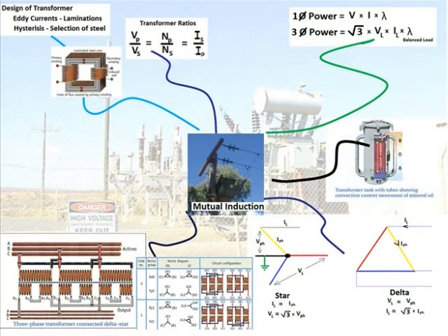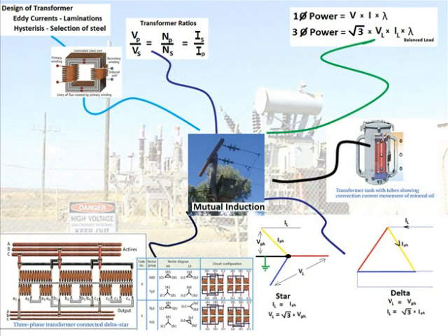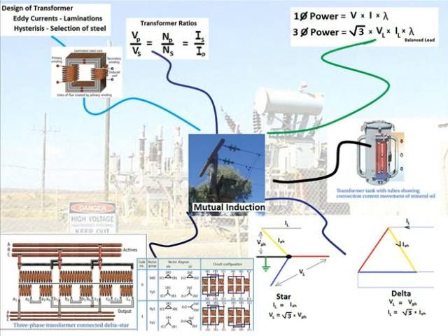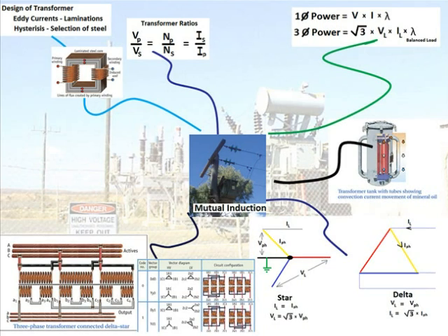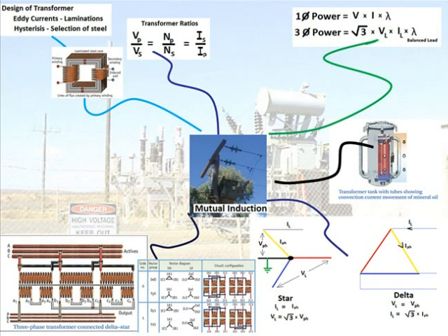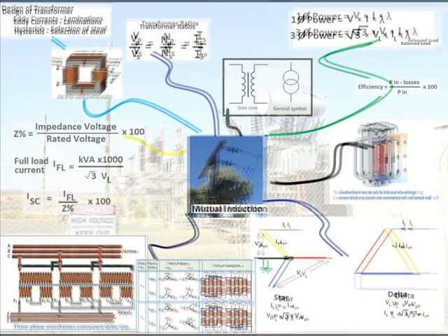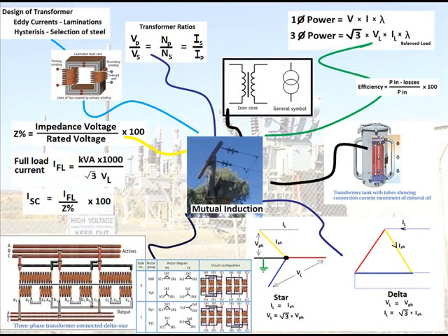Construction of transformers, of course, needs to take into account the ability of cooling. In many cases you'll have oil-filled transformers, just based on convection, which serves for both insulation and cooling. That can be increased, of course, by the use of pumps, radiators, and so forth.